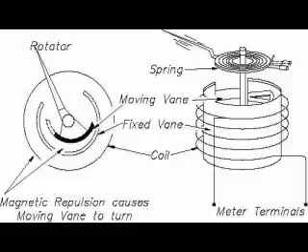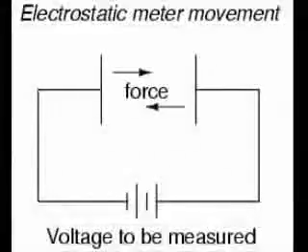Some meter movements are polarity insensitive, relying on the attraction of an unmagnetized moving iron vane towards a stationary current-carrying wire to deflect the needle. Such meters are ideally suited for the measurement of alternating current, or AC. A polarity-sensitive movement would just vibrate back and forth uselessly if connected to a source of AC.